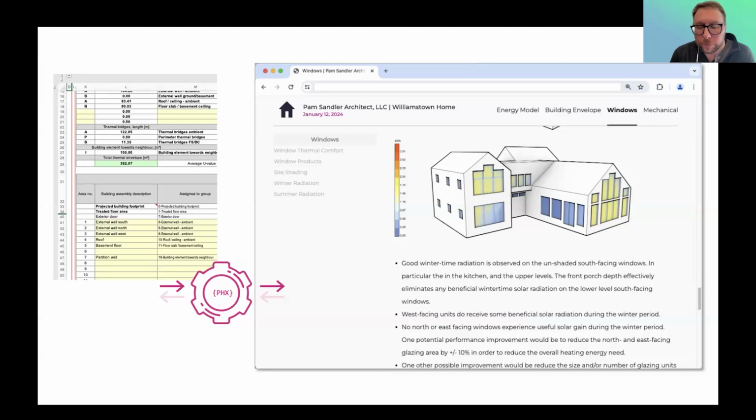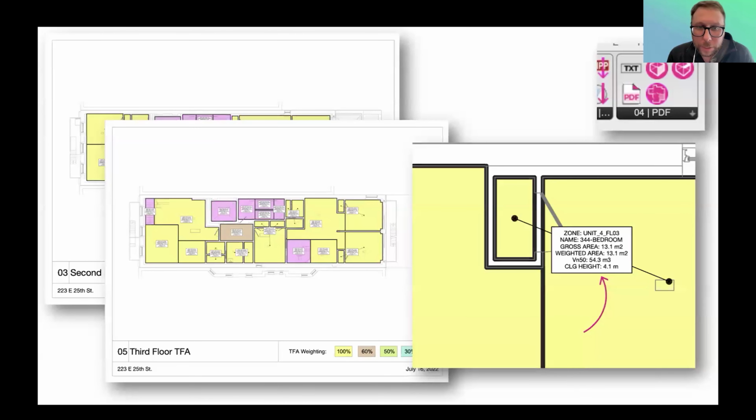If you can standardize those and automate those processes using these types of behind-the-scenes tools, that can significantly improve your overall workflow. Of course, things like typical architectural graphics are also going to be required in many cases. One of the nice parts here, though, is because we're building, and this is not revolutionary, right? This is just BIM. Because you're building a rich BIM model, you don't write in the name and a tag. You just use a tag object, which is able to pull that data out from the underlying BIM object and create these types of documents automatically. So that's a really important part of the workflow.